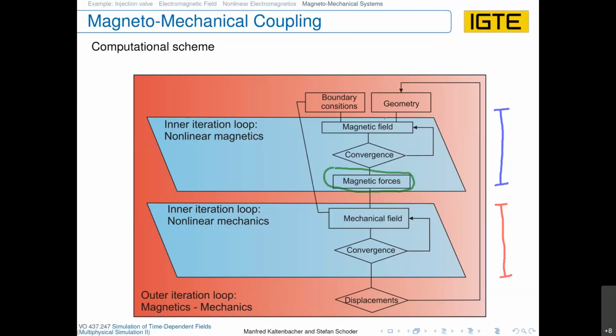We have to compute the magnetic field. Please consider it on the updated geometry. Yeah, so we have to add the mechanical displacement to the coordinates of all the finite element nodes where we compute the magnetic field. If these displacements are too large, you have to do some smoothing, as we have discussed.